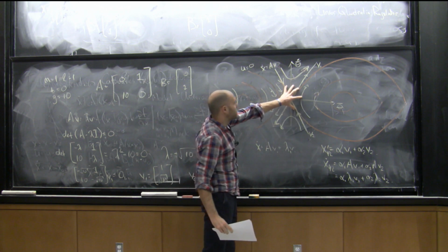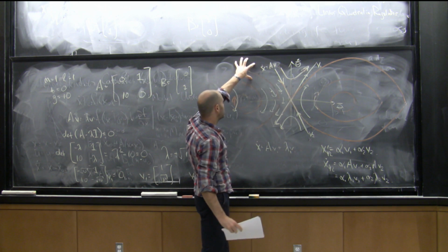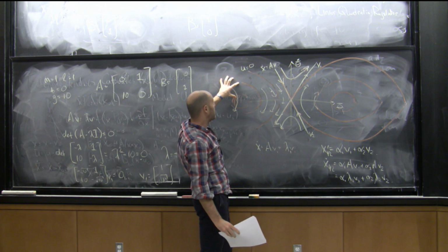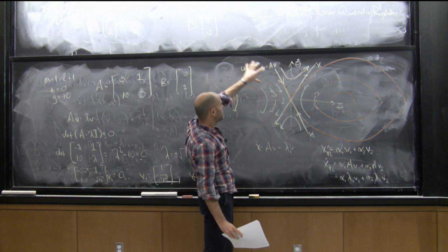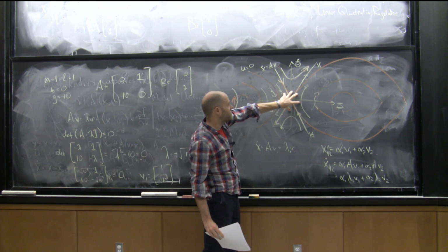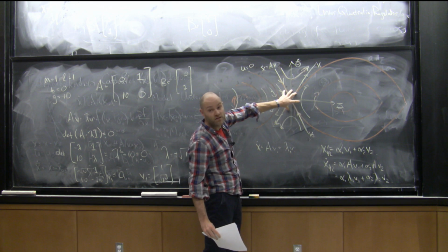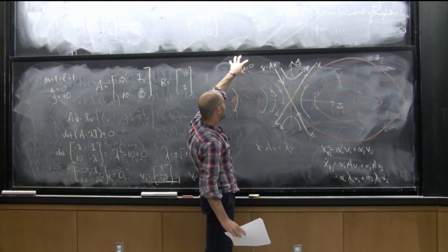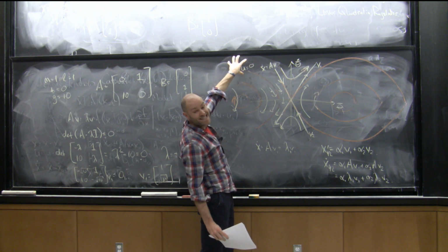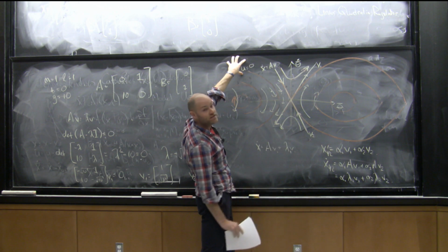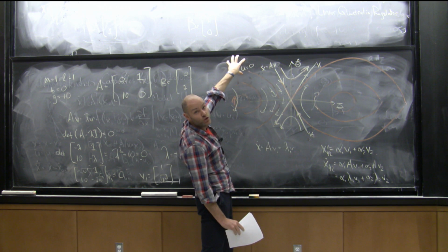Now, one thing you'd like to do, and this might inspire you to think, okay, I'll just linearize here, and then linearize over here, and over here. And you can do that, but you open up a much harder problem. In this system, this is a linear system that has a fixed point inside its set. We can call LQR on this and be happy. If you try to take a first order Taylor expansion around a point that is not a fixed point, then that f of x0 didn't disappear. So you have an affine system there instead of a linear system.